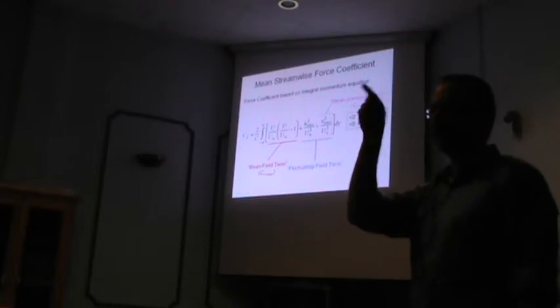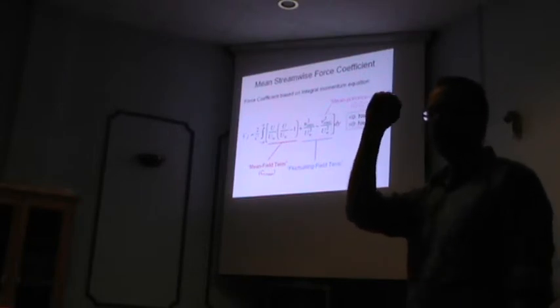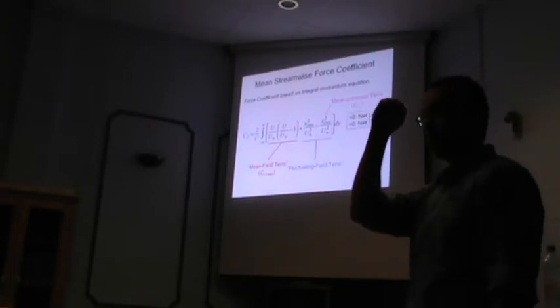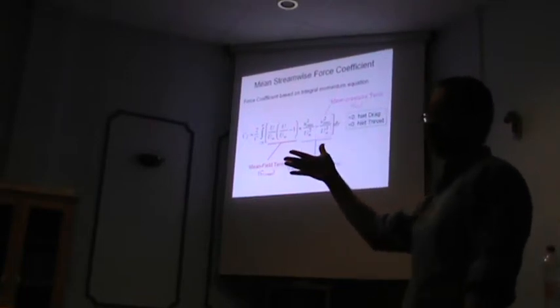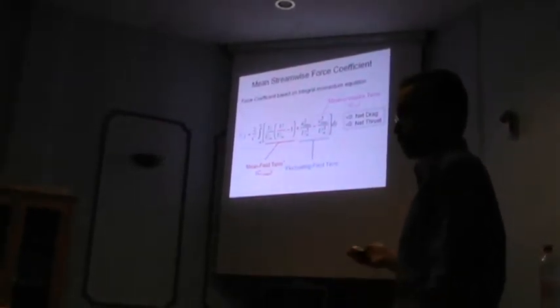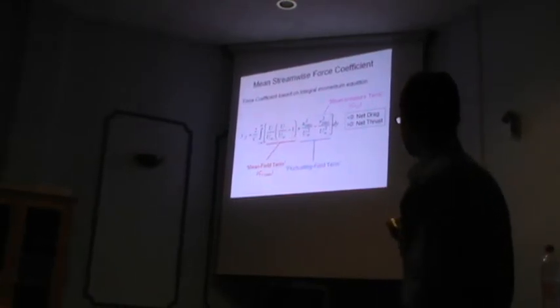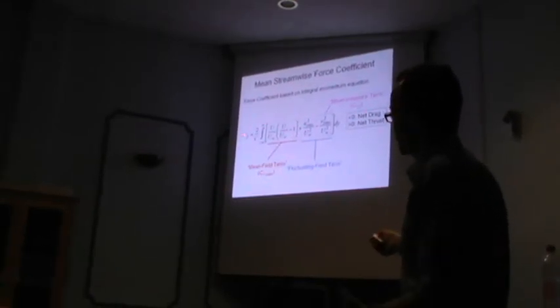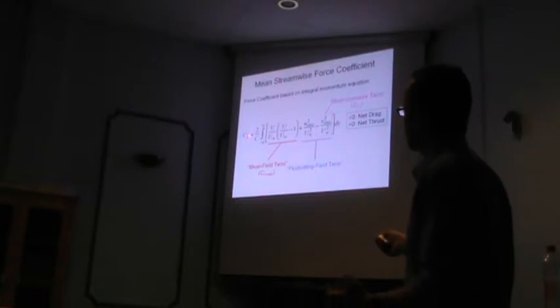The stronger a vortex is, like a tornado, you produce a low pressure core inside it. You get low pressure, and that produces a net pressure drag in your integral momentum analysis. So remember, this CF is really what you care about ultimately, but it has 2 important components, one from the mean field and this mean pressure term here.